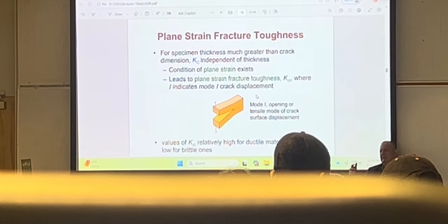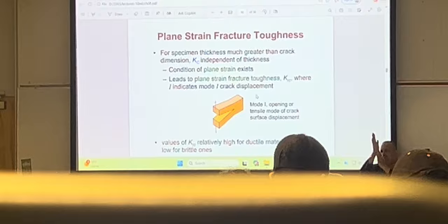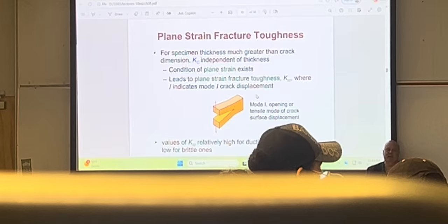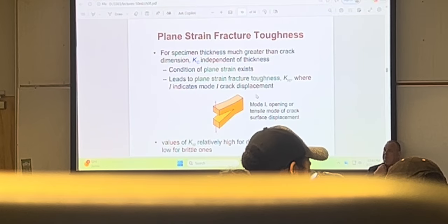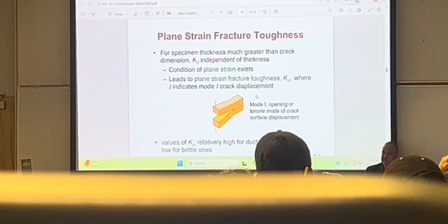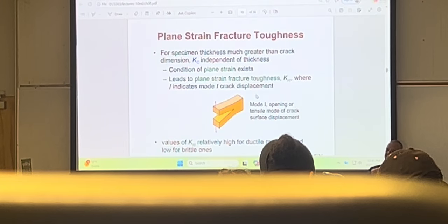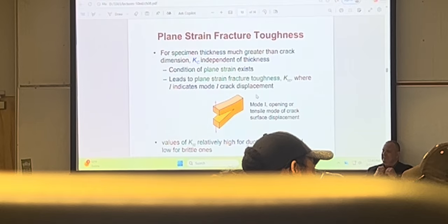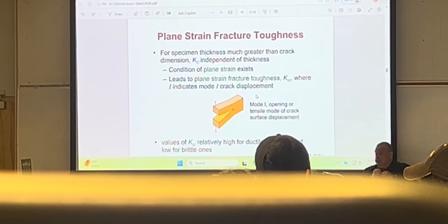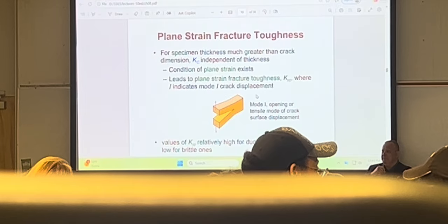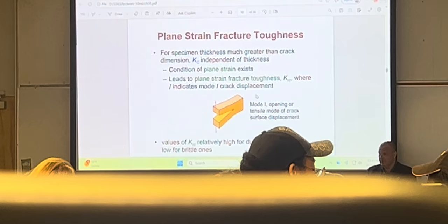We don't discuss it, but actually there are 3 modes of fracture. There's mode 1 like this. There's mode 2, shear like that. And mode 3 is twist. As you can imagine, I have this shirt example. Imagine I rip it like this. The first button is going to go, then the second button is going to go, then the third one. And then if I pull hard enough, I'll rip it further. Can you imagine it?